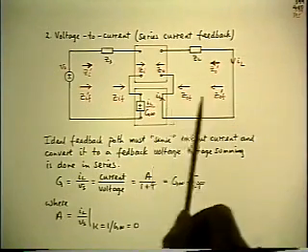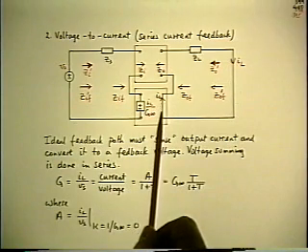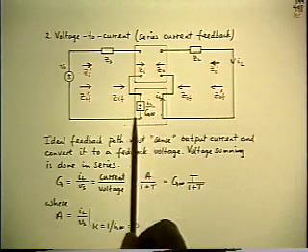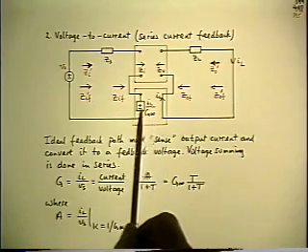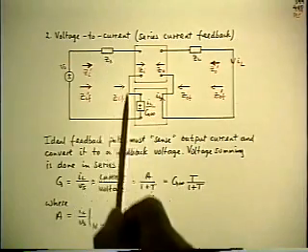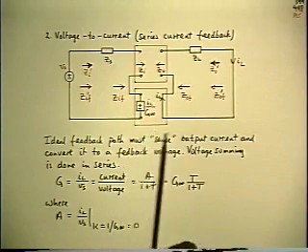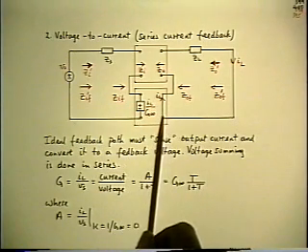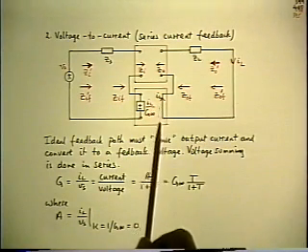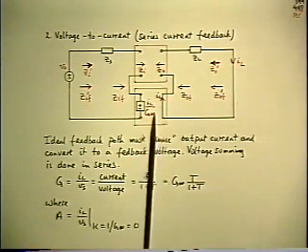So now you sense the output current IL by connecting the feedback box in series and sensing the current. The feedback box then converts that sensed current into a fedback voltage, which again is voltage differenced with the input signal by the series opposition connection. So this is the standard current sensing, and ideally you want to sense the current with a zero impedance. In practice, you do it by a very small resistance, an ohm or a fraction of an ohm, or you can do it by a current transformer.